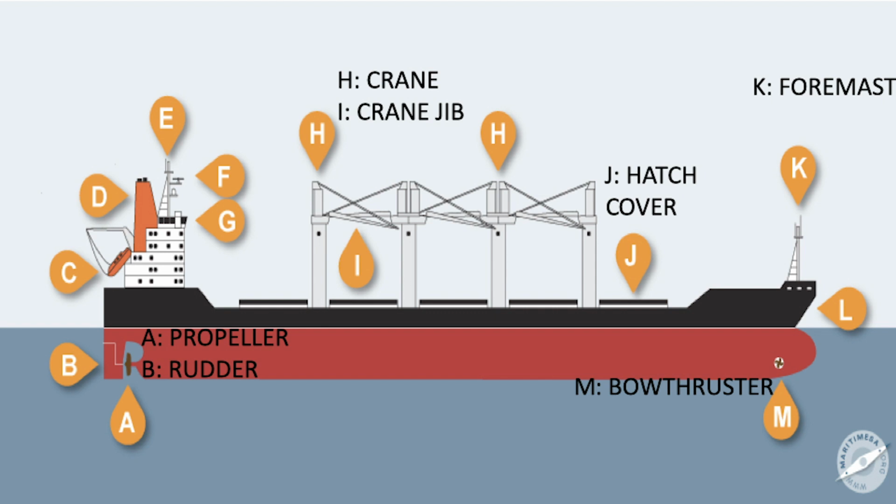On some ships, the propeller shaft, and therefore the propeller, can turn in the opposite direction, causing the ship to go astern. In other ships, the propeller keeps turning in the same direction, but if the ship should need to go astern, the angle of the blades can be altered to change the propulsion, causing the ship to go astern. This is called a variable pitch propeller. There are other forms of propulsion that are used in some ships: multi-directional propulsion, such as the Voith-Schneider system, azipods, sometimes linked to a dynamic positioning system.